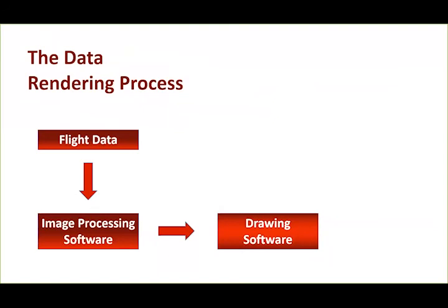Since the point cloud is 3D, you can build a coordinate data table of XYZ and then apply the descriptors of those points that you're selecting, as if you were mapping with some type of EVR software from a total station, and then allow the CAD program to do the line cutting if you want, and continue to map and diagram no differently than you were working with total station data. Again, one of the other outputs of most of these photogrammetry programs is an orthorectified mosaic TIFF file.